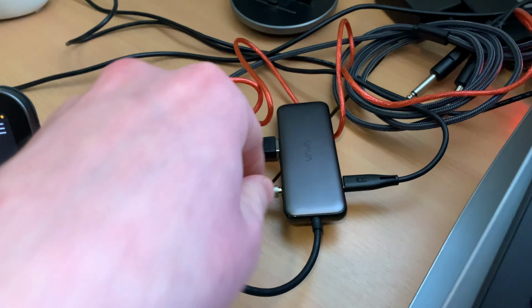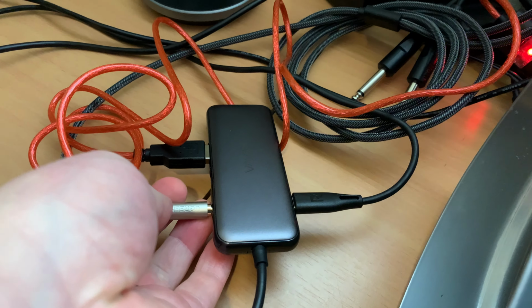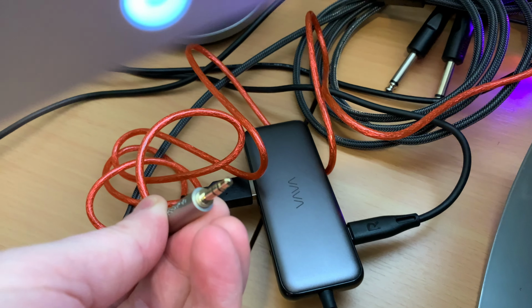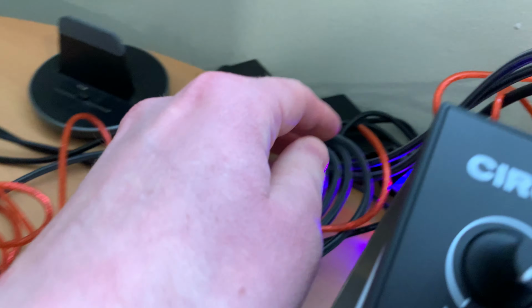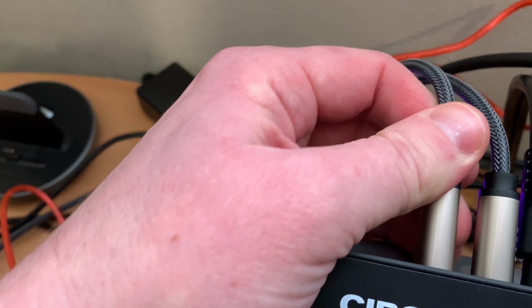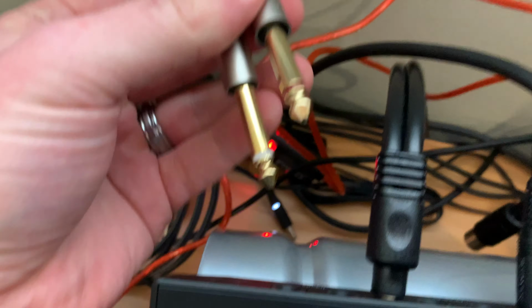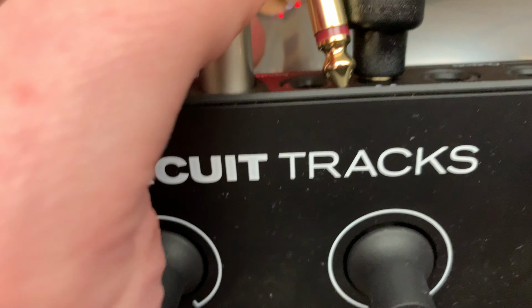And then the next thing that you'll need is an audio cable that has, I believe it's 3.5 millimeter, on one side, so like a normal headphone jack, or whatever jack is on your dock, but normally it's a headphone jack. Plug that back in real quick, and then that'll go out to two 1/4 inch jacks, so left and right, as you can see here, and then you plug those into the input on your Circuit Tracks.